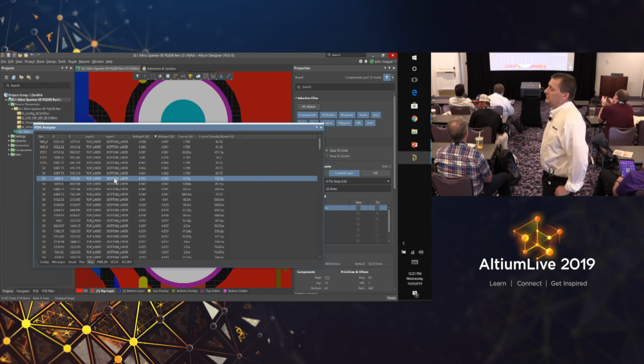The best way to do that now is just through multiple configurations, so snapshots in time, because there is no simulation relative to time. No, I'm sorry, for temperature. Well, not over time, just where we would do a maximum current, and it would say, hey, you said this is going to rise a maximum of 10 degrees, but you're actually going to hit 15 degrees above where you want to. We'd see more of a temperature map. It's very similar to the current density one, right? It's just a different way of viewing it.